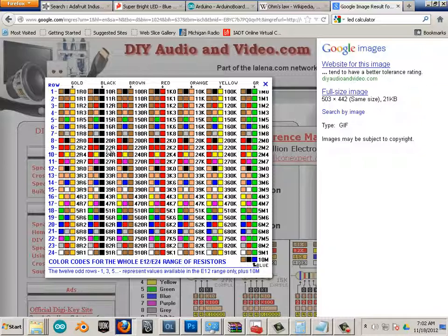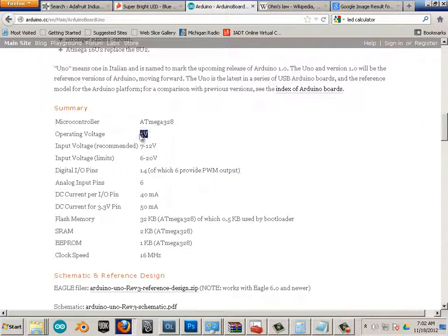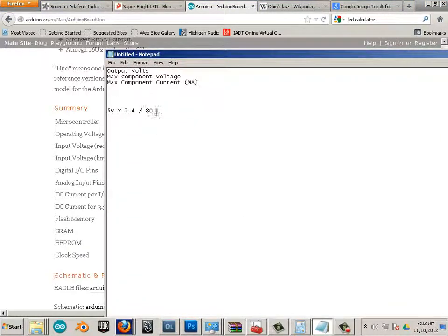Cool. So that's how resistance works. I wanted to save the LED. I could have gone here to make it brighter, but the fact is I had to dummy it down because the LED could only handle 3.4 volts and the Arduino unit was putting out 5 volts. So I used Ohm's law to figure that out. Pretty cool, right? So keep Ohm's law handy and use it wisely.